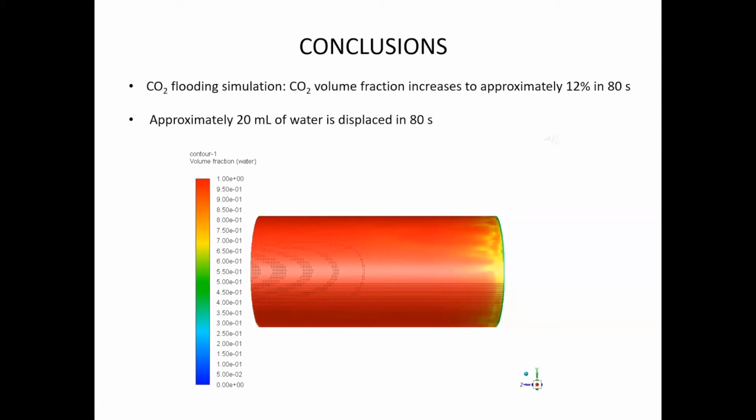It's actually very slow, but you can eventually see some green there, which means that the volume fraction of water has dropped from 100% to about 50%. And with time, I mean, this is only 80 seconds. I guess I would run the simulations through 1,000 seconds or maybe more, and then you would see that water is being completely displaced from there. Okay, and then